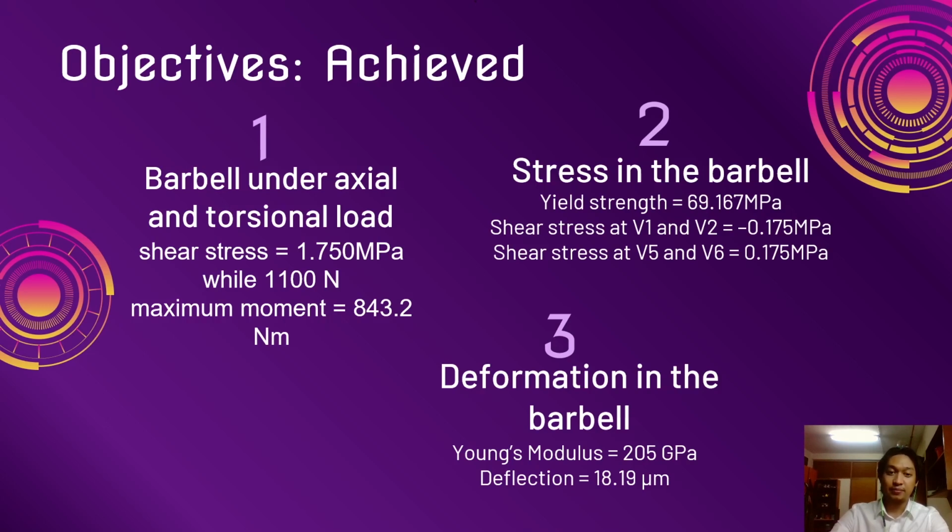Third, the deflection that occurred in the barbell was calculated to be 18.9 micrometers from the Young's modulus of the bar, which was 205 gigapascals.